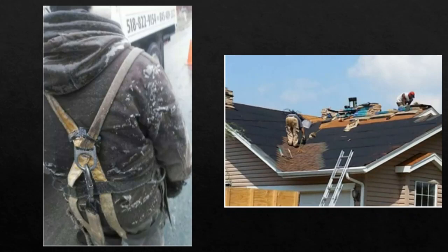And in this other picture, it doesn't look like we have 3 feet of overhang on that ladder that's gone up to the roof. So when these workers have to descend, it's not going to be easy for them to get on that ladder and to safely go down from it. Plus, it looks like the angle is a little bit more severe than the 4 to 1 that we normally like to see.